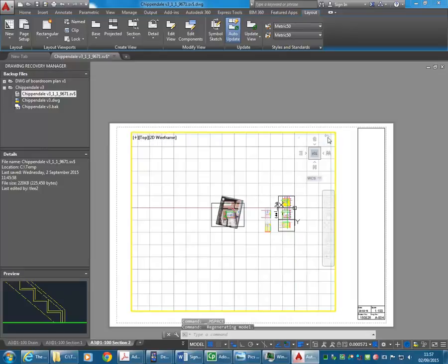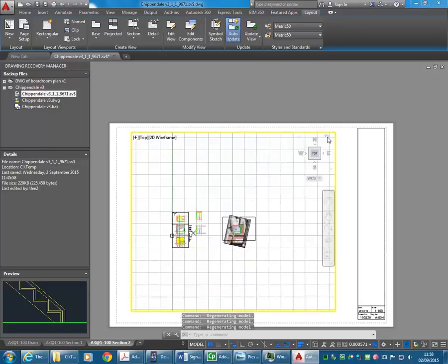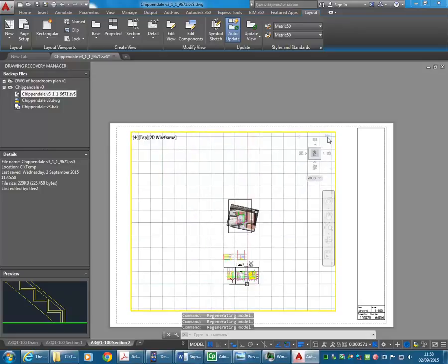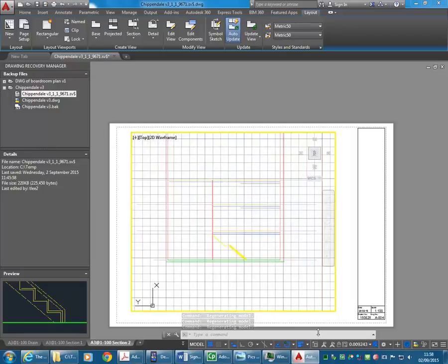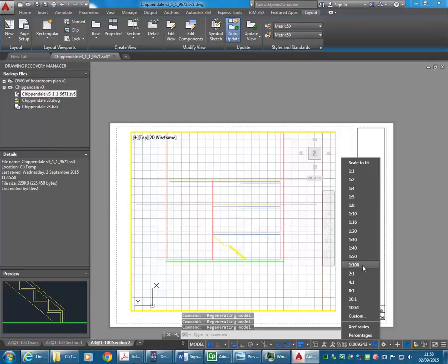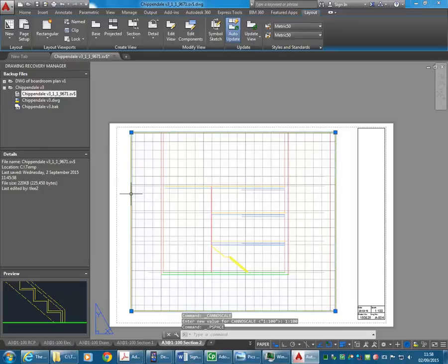Can you type region in a viewport? Oh yes, absolutely. They're a graphical menu sort of option. So here we just need that arrow. There are other ways of rotating the view using the UCS command and things like that, but it's nice to have these arrows. So there is my new section, and now I can set the scale and back in business. It's into my viewport layer.